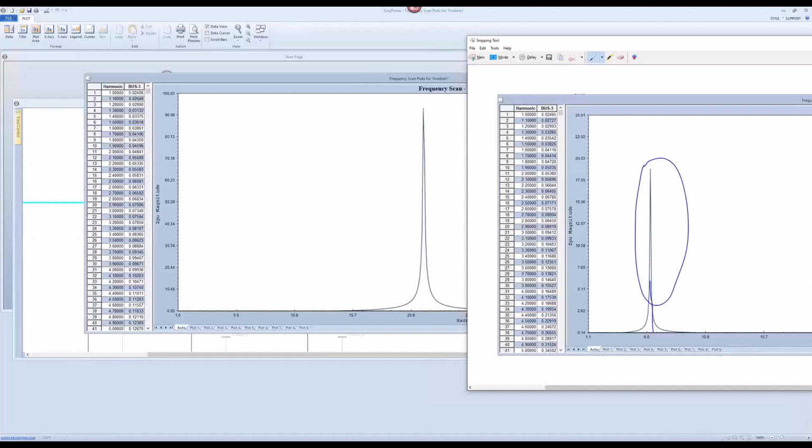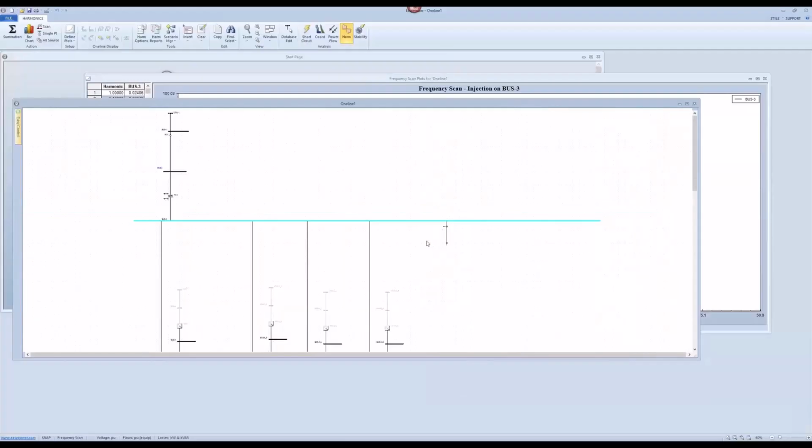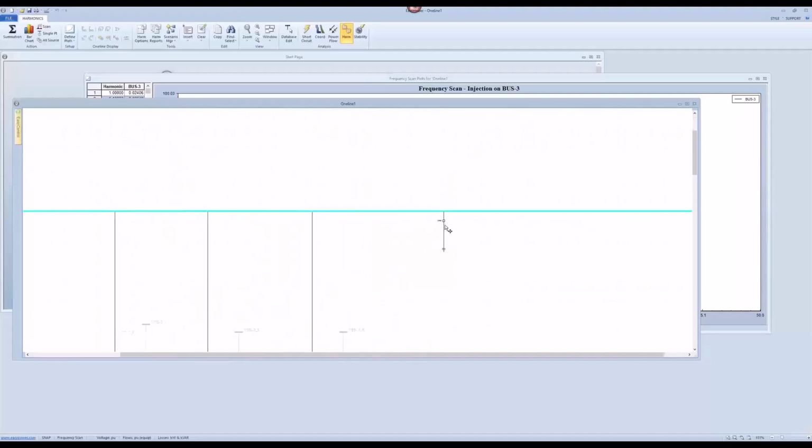So you will have lower order harmonic violations if your inverter is going to inject harmonic current at the lower harmonics, right? That is why many people still like to design capacitors as reactive power compensation to comply with the FERC order 829. But actually, you have other concerns as well. When you introduce a new resonance point to have harmonic issues, for 2800, it may not be such a big issue. But if you are still using the IEEE 519, considering the system strength, you may have an issue. Even with the 2800, you may still have an issue as well because you introduced those resonance points, right?